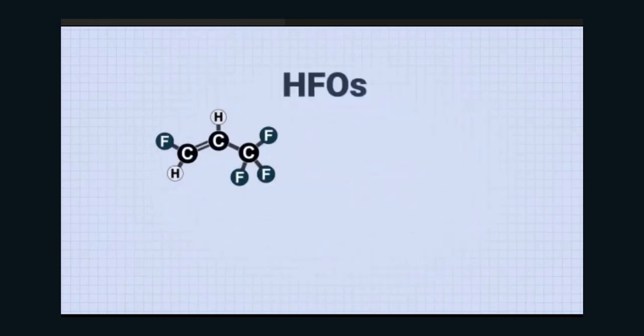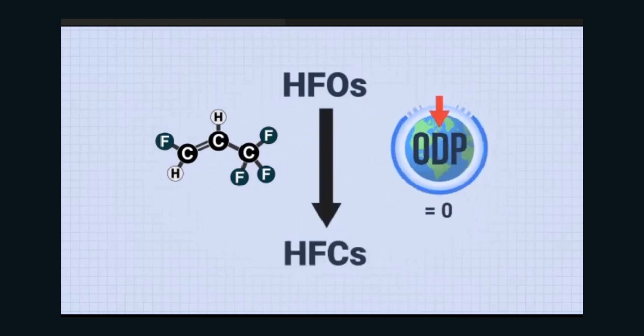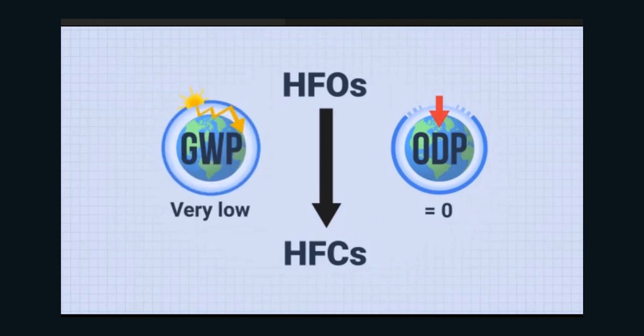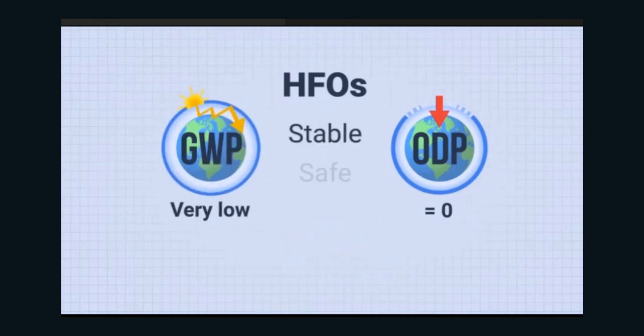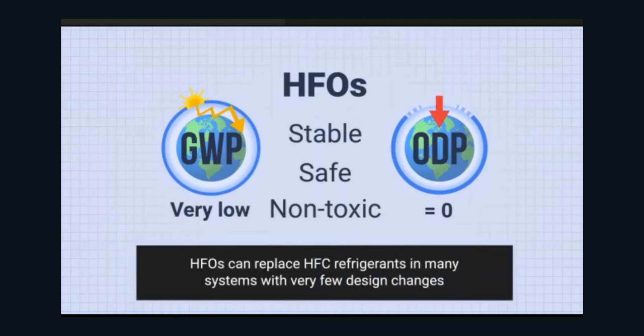Hydrofluoroolefin, or HFO, refrigerants have been developed as a replacement for HFCs. HFOs have zero ODP and very low GWP. They are stable, safe, and non-toxic, and can replace HFC refrigerants in many systems with very few design changes.